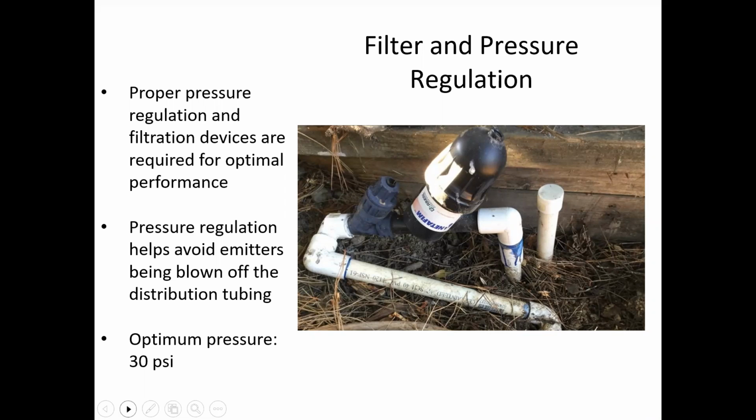And I don't know if you remember before, but we were talking about spray heads that required PSI of 40, 50, significantly higher. So this just shows that having those smaller tubing, the emitter rates, emitting water at gallons per hour really requires a significantly lower pressure, which is why it requires its own pressure regulator on it individually.